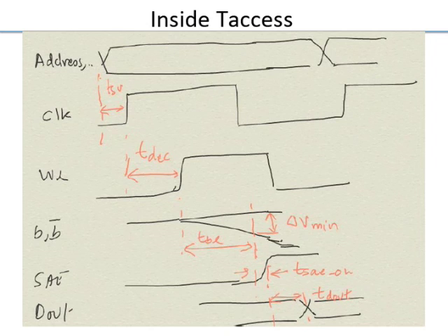But again, it's not a good idea because it's more important from a system level to have more memory rather than fewer memory cells with larger size. So you are only left with the option of capacitance. And capacitance you can reduce by basically architecting. Instead of having 128 rows where the bit line column runs across 128 rows, you might say, I'll go for 64 rows, or maybe 16 rows, come down all the way. So that becomes more of an architectural study because every time you reduce the size of the bit line column, you have to introduce some extra circuitry which adds to the overall area. So you have to do that analysis.